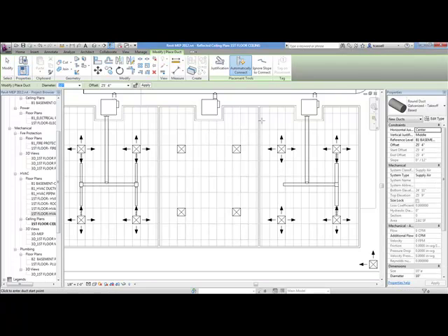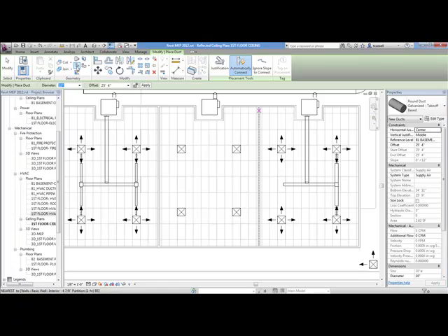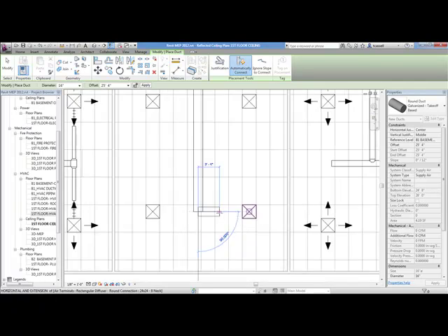When I go to create the duct, it's just a matter of saying, what type of duct do I want to create? You know, I really want galvanized round duct, and I really am going to need 14-inch round duct coming off this unit. It's just a guess for the moment, but it's what we'll use. So there's some 14-inch round duct coming in off that unit. It's going to run all the way down. And right here I'm going to branch off and take a corner.